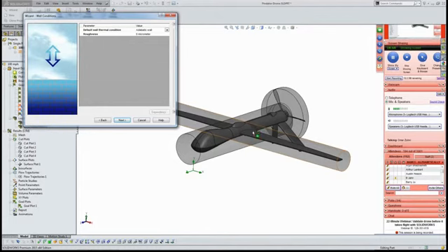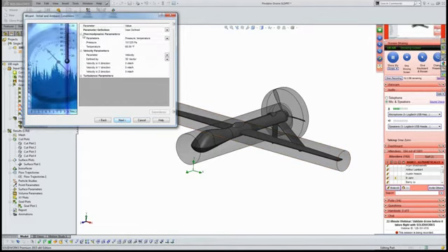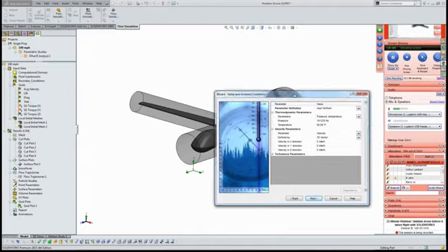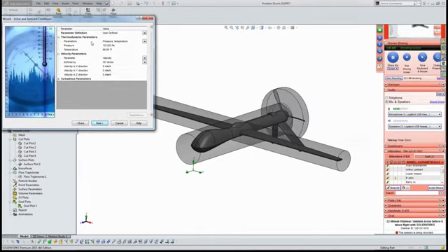If you knew the surface roughness of your drone and you wanted to account for it in the turbulent boundary layer, you could account for that here. And finally, it asks, what do you want your thermodynamic parameters to be? If this drone was flying up in space or up in the atmosphere, it's going to have a different pressure and different temperature, so you could specify that here.